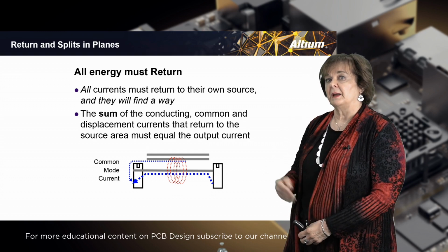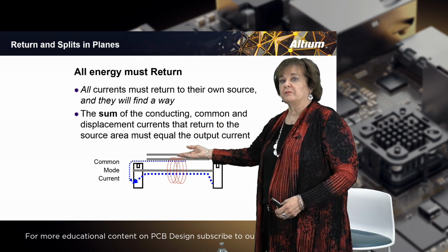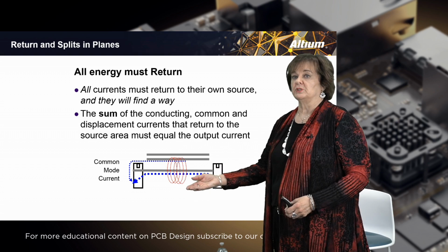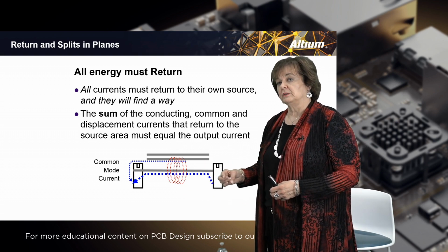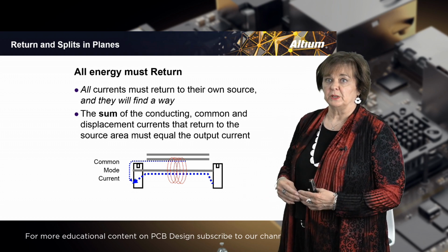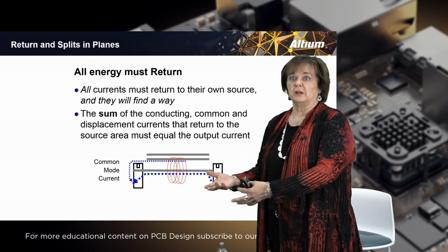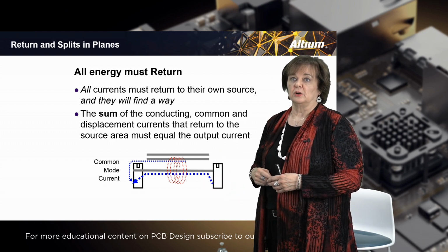Even signals that happen to have spread over to other signals have to then find a path back to the original source of that particular IC, and they will find a way. It will be very, very low energy, but it could still couple together with other energy and cause some issues.